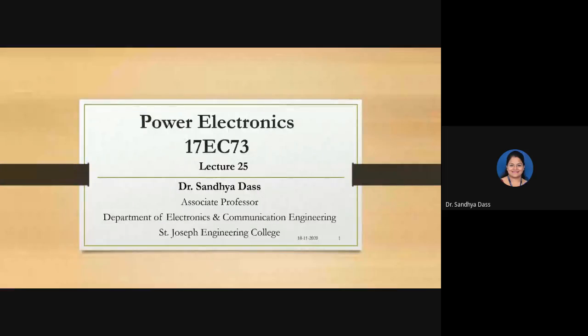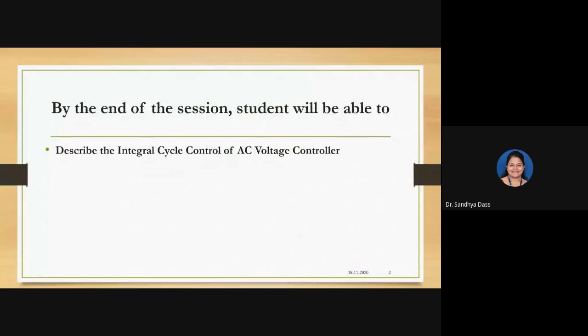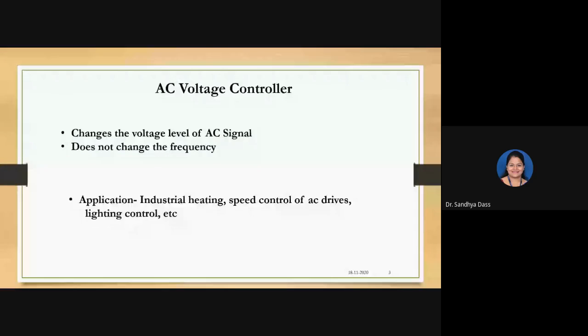By the end of today's class, you will be able to describe integral cycle control of the AC voltage controller. When we say AC voltage controller, it changes the voltage level of the AC signal at the load. But there will not be any change in the frequency.